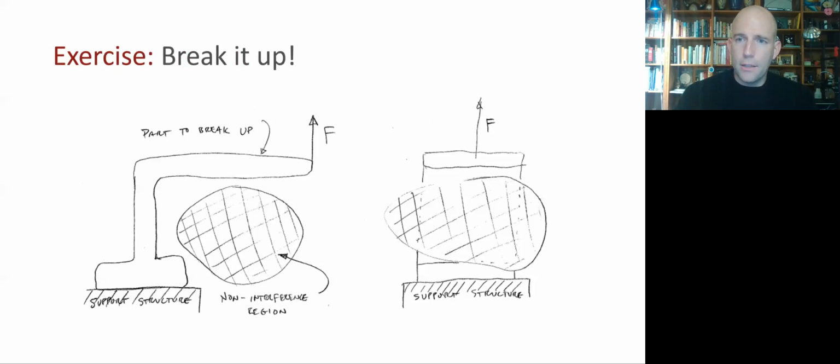And then pick one that you like and do a free body diagram analysis. Try to figure out what is the force multiplier. And that should take 5 or 10 minutes. And then take a step back, look at your analysis and think about what it tells you about what dimensions should be big, what should be small, and maybe sketch one more final candidate design that embodies the lessons you learned from the back of the envelope analysis. So the whole thing should take about 15 minutes and take your time. All right, you should hit pause now.